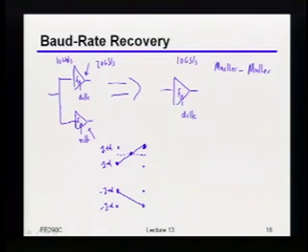By the way, what should that threshold be? Is there some other comparator that we might have in our system that might just happen to sit there anyways? DLEV. Yeah, it's the DLEV comparator, right? That's exactly where you'd put DLEV, okay? Now, to be totally fair, you might actually need another one down here, but in principle you don't necessarily have to. I should say this is negative DLEV, so to speak, okay? But indeed, if you were to do something like this, then you could use the information coming out of the DLEV comparator to also try and find the right symbol timing, okay?